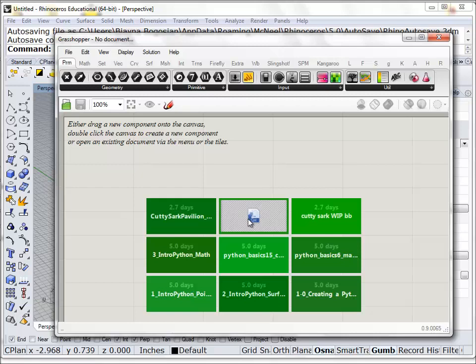As the name indicates, parameters are going to be in a way the kits that we're going to play with. From, let's say, certain geometry types that we're going to reference in the Grasshopper environment, to numerical values that we're going to use to then change our variables. Anything that has to do with transferring geometry or inputting geometry is going to be here.